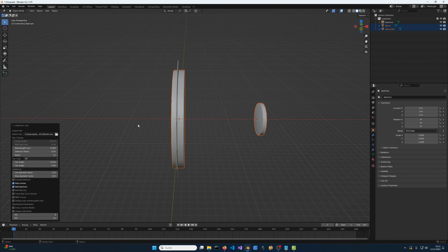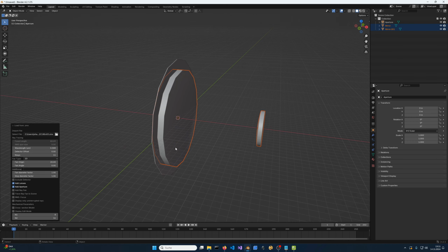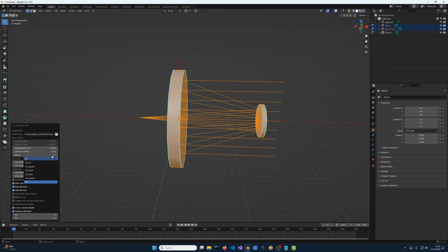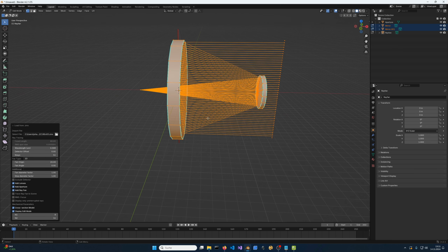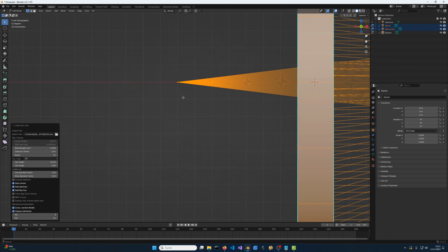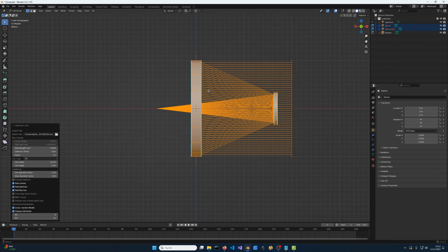And this specific type of setup here is called a Cassegrain mirror. So the primary mirror is parabolic and the secondary mirror is hyperbolic. When adding a ray fan in edit mode, we can see that the ray fan first hits the primary mirror, is reflected off it, hits the secondary mirror, and then forms a very nice focus spot on axis with a really low RMS spot size. And also the focus location in the zmx file is already really good for this design.